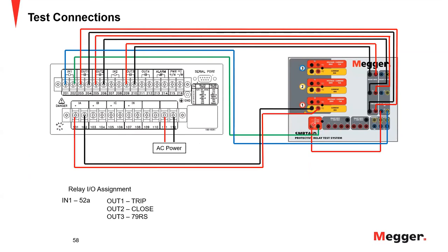The idea is to put an output contact. This contact is just a dry contact. It's isolated from the test set. It's controllable by the logic, so you want to series the contact, the input to the relay, and the voltage all together. So in this situation, you come out of the positive into the programmable contact, out of the contact, all the way over to the input, and then from the negative side of the input back to the negative of your battery source. The idea here is you're just needing a switched DC system right here.